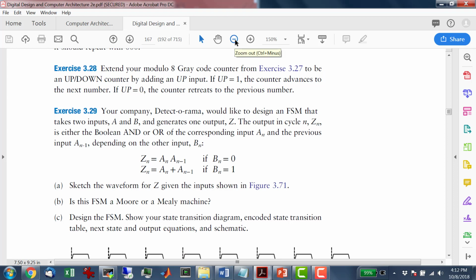Well, for my next state table, I don't really care what b is, right? So I could build my next state table just as a function of the current state. So if this is state 0 and that's state 1, then I could say current state 0, 0, 1, 1, and then a 0, 1, 0, 1, and then next state. In fact, I think that in this case, the next state doesn't even depend on the current state. It's a don't care.